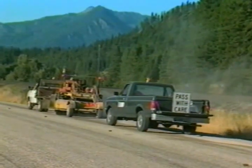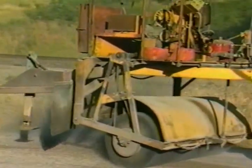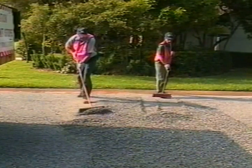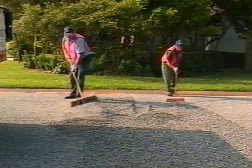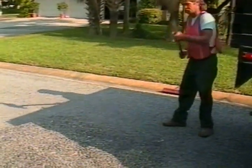In rural areas, the loose aggregate may be broomed to the shoulders of the road. In urban areas, however, they should be broomed to the curb or center line and then removed manually or by vacuum device.